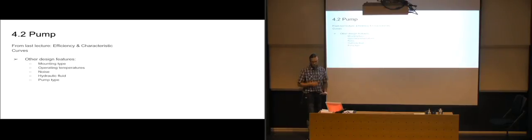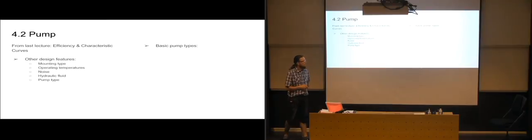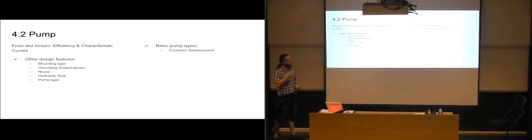And then the type of pump will also be important for our design. And we're going to start looking at those in a little while, the different types of pumps. So we have quite a few basic pump types here. So we have constant displacement, where the amount of volume that you are moving for each rotation stays the same. So it's a constant volume. So as long as you're keeping the amount of revolutions, the RPMs, at a constant level, you will also be moving a constant volume through every minute.